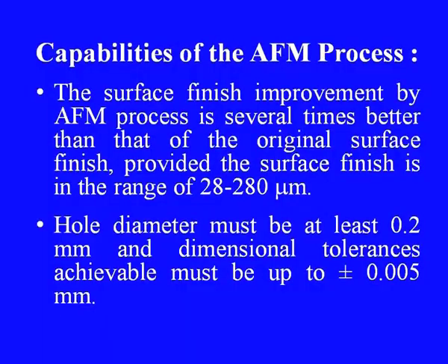Now, let us look into the capabilities of the abrasive flow machining process. The surface finish improvement by this process is several times better than that of the original surface finish, provided the surface finish is in the range of 28 to 280 micrometer. Even better surfaces have been reported with this process.